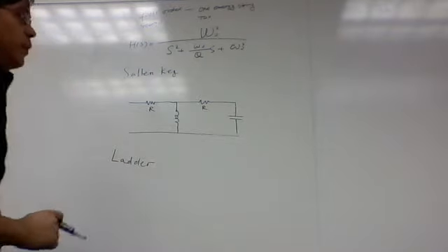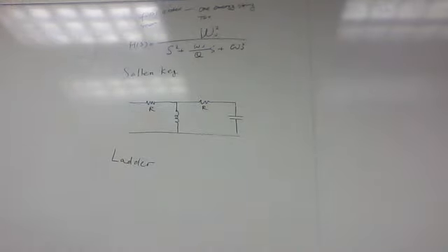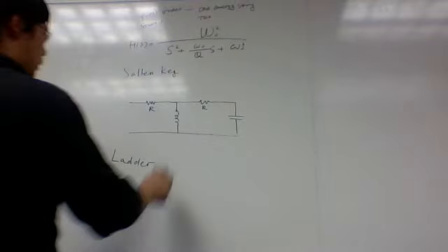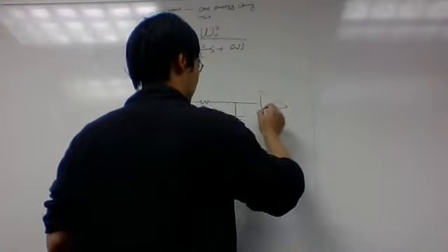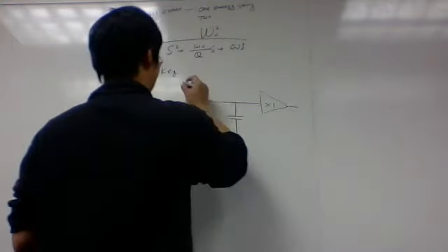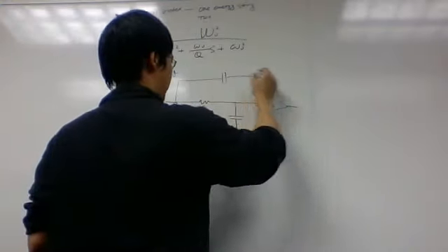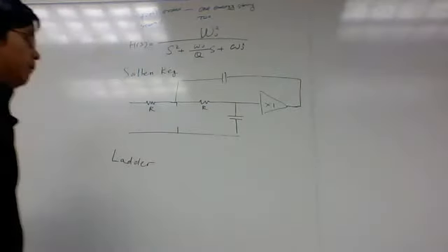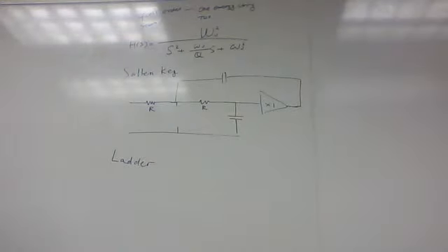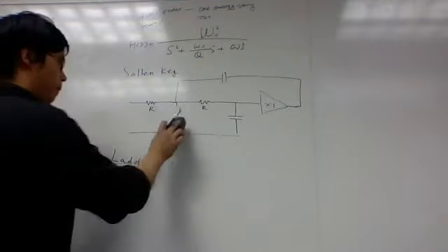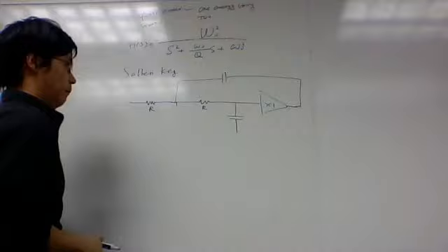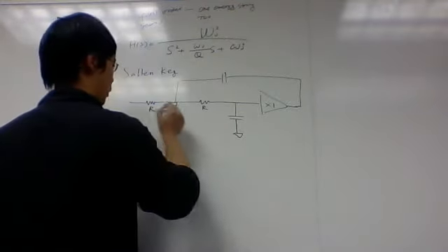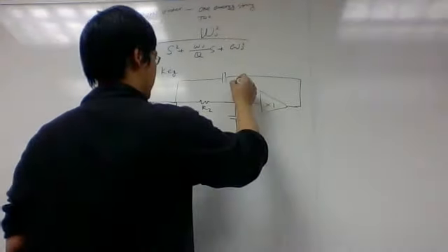But there's no inductor in it, since that's not done easily. So what you do is use a gain of 1 and some sort of positive feedback to mimic the inductor. It's R1, R2, C1, C2.